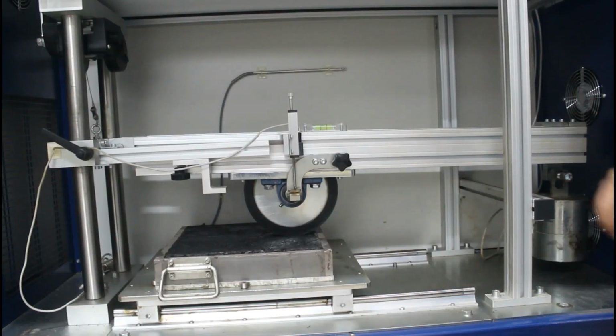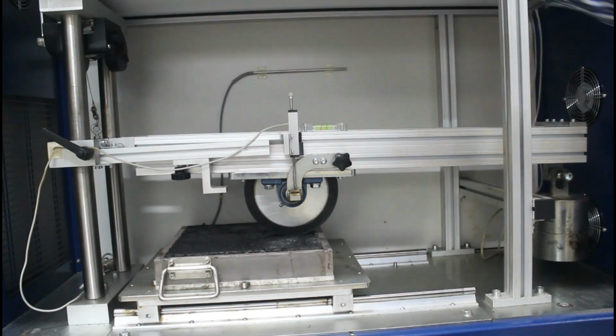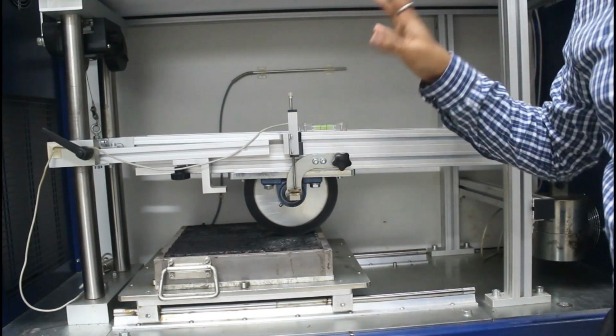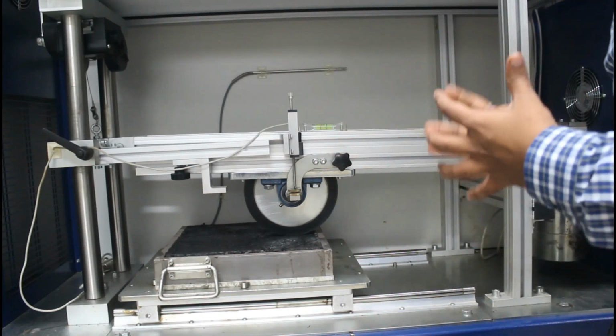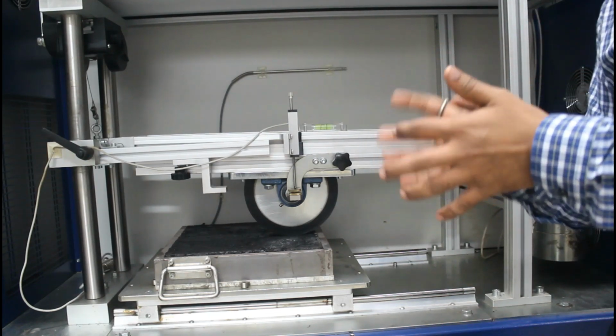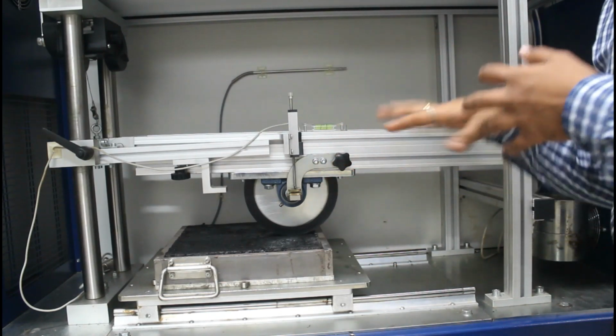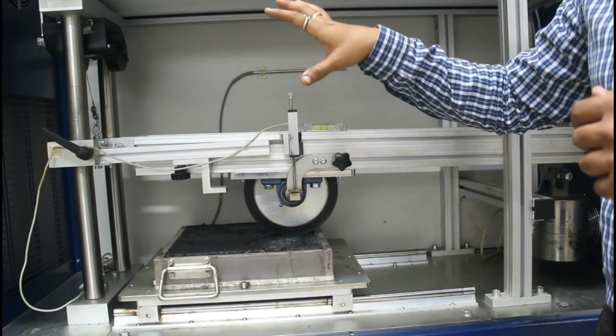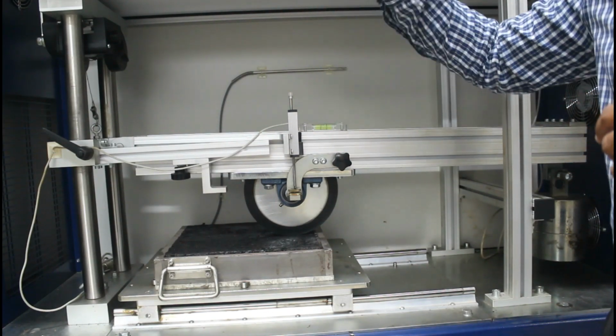So you can see here basically it's a thermally controlled chamber. It means you can set whatever temperature you want, like 60 degrees, 50 degrees, whatever the expected temperature in your field is, right? Wherever you want to test the bituminous mix, the temperature can be set in this particular chamber. It has heating coils and some fans distribute the hot air.